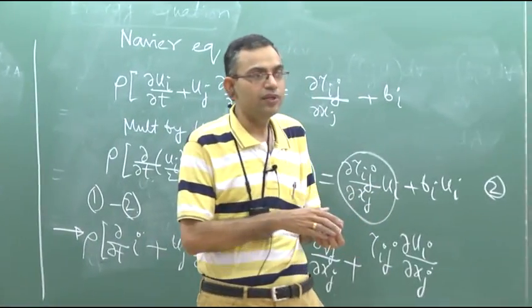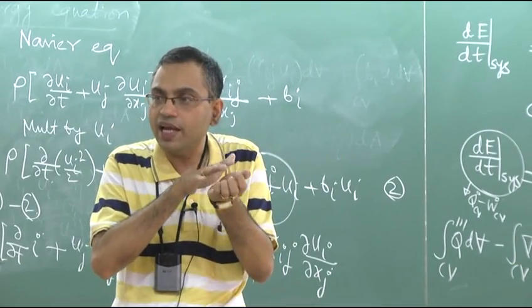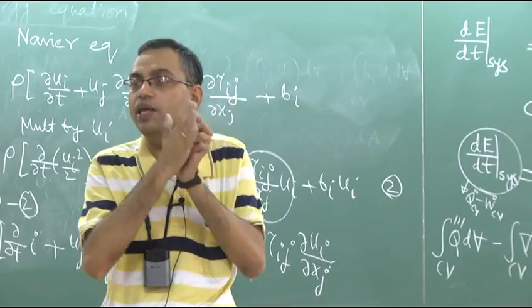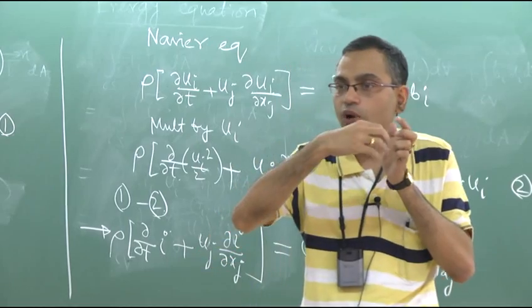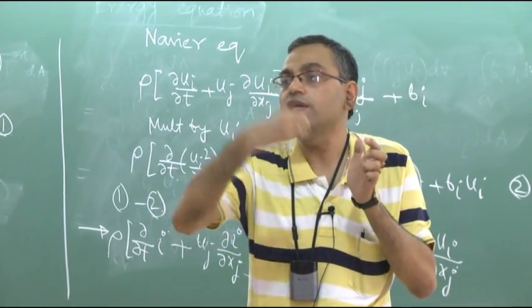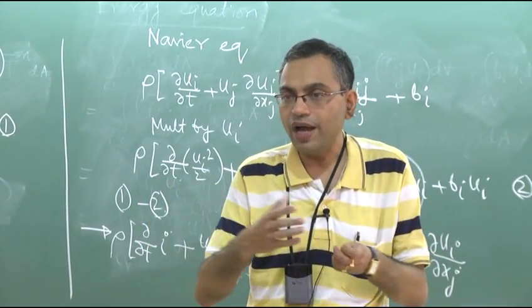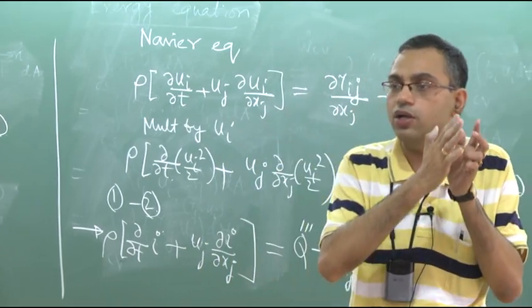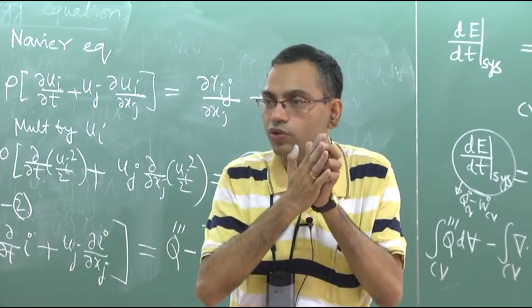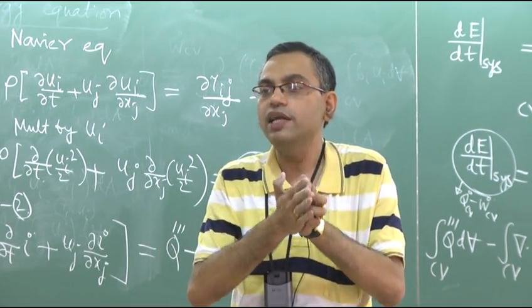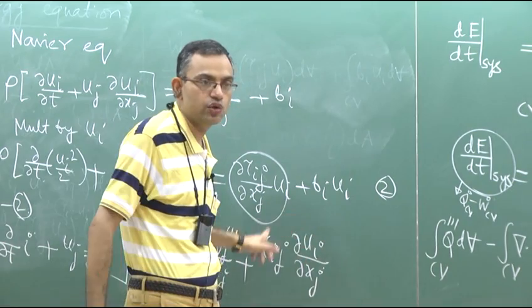It is something like this. Let us say that you have shear in the flow. If you have shear in the flow, then two layers of fluid are sliding against each other, as if you are rubbing your palms. This work is not utilized, but is irreversibly converted into internal energy through viscous dissipation. So this is called viscous dissipation, where there is an irreversible conversion of work to intermolecular form of energy. If you rub your palms, you cannot get any work out of that, it simply will generate heat. So it is effectively like a heat source.